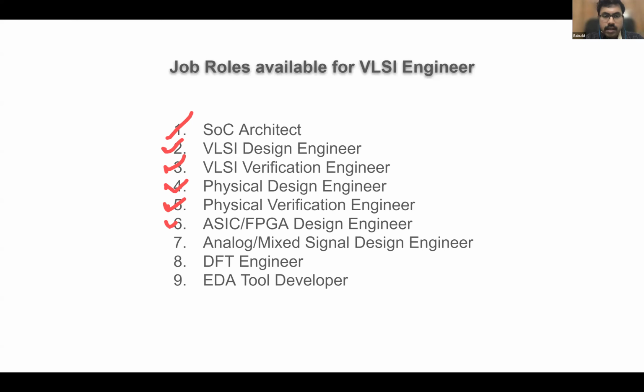Then we need to check whether the design is compatible with the hardware or not. That is where the role of the FPGA design engineer comes in. He will be checking the entire binary code generated from the RTL. He will be dumping it inside the FPGA, that is the general board. Before going to the manufacturing foundry, we need to properly check whether the code is compatible with the hardware or not. Then, along with the digital components, we will have a lot of analog components also associated with the chip.